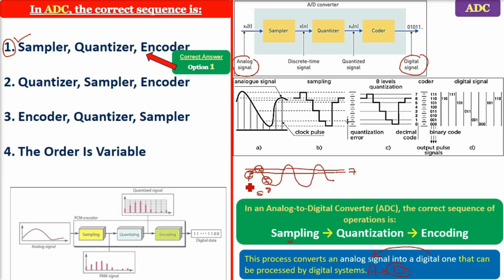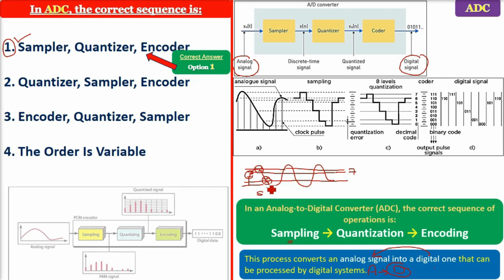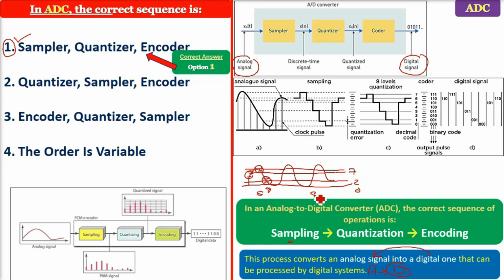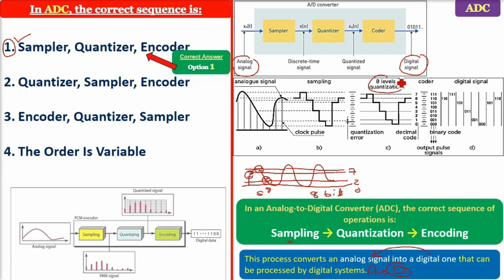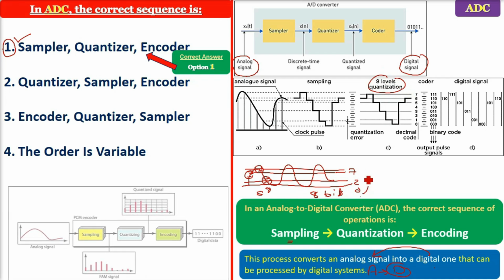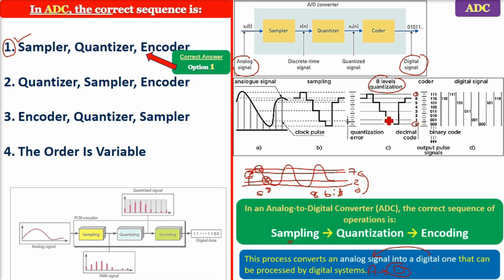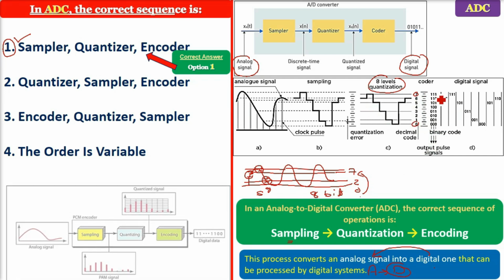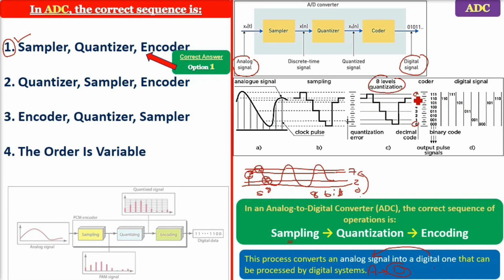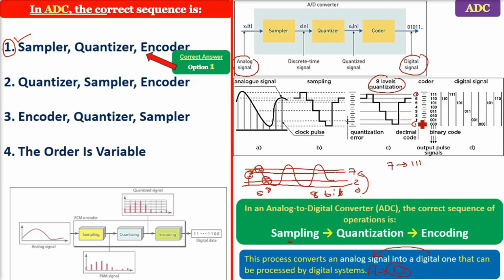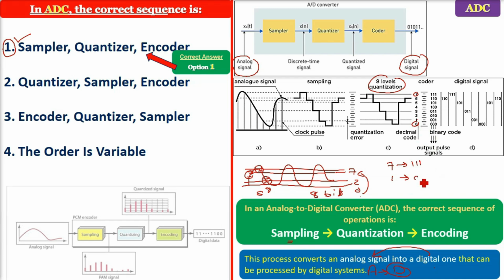In quantization, the sampled signal is quantized, meaning the continuous amplitude values are mapped to a finite set of discrete levels. So we are giving, say, 8 levels in this case. So every sample will have a target 0 to 7 category. Now from 0 to 7 we give them a code. For example, 7 will be known by 111, the 4 will be known by 100, the 1 will be known by 001. So every quantized signal is now given the encoding scheme, the encoding number.